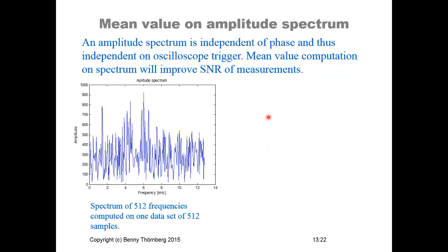The frequency transform and the amplitude spectrum of the frequency transform behave in such a way that they are not dependent on the phase, and the phase describes where the waveform actually starts, how it is delayed in relation to the origin. The frequency transform is actually complex valued on its output, and you are computing on these complex valued samples in the frequency domain.